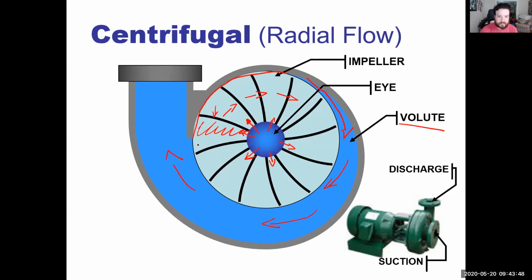All right. And that's the important thing to see. It's constant. And that's why these pumps aren't self-priming, because they're not going to be able to take in a constant volume, whether it be air or a fluid that is going in it. It has to be filled almost to the top to actually start up and run.